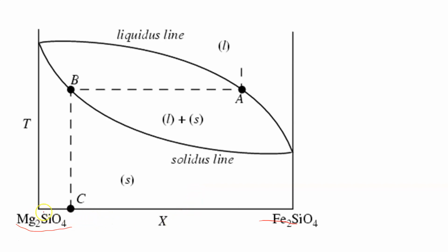Number one, the x-axis is the percent of a particular alloy, and the y-axis is the temperature, right? Now, down at the bottom below this particular line, known as the solidus, everything is solid metal. So we've got the lower area here of solid metal. We've got the upper temperature here, which is the molten metal. And these two lines, again, I already said this was the solidus line. This is the liquidus line, where things transition into a molten metal.